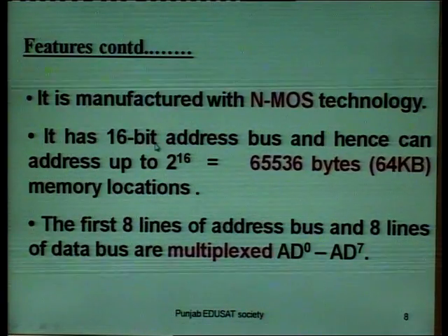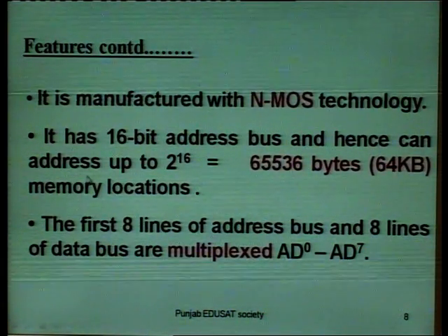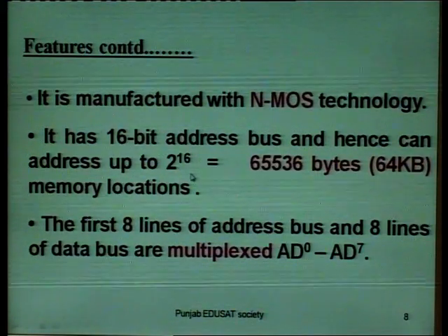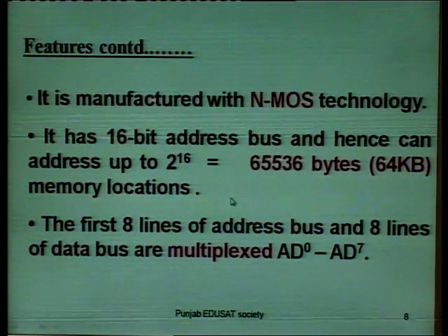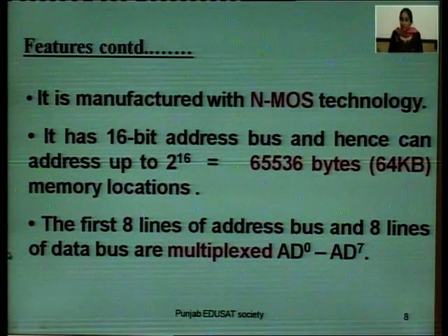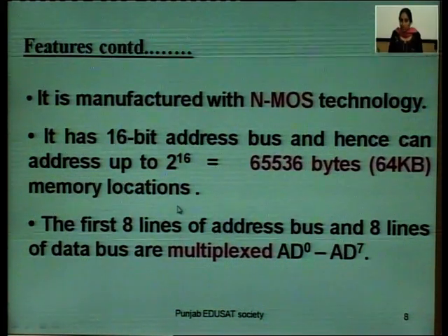It has 16 address bus and hence can address up to 2 raised to power 16, that is 65536 bytes, that is rounded to 64 kilobyte memory locations.